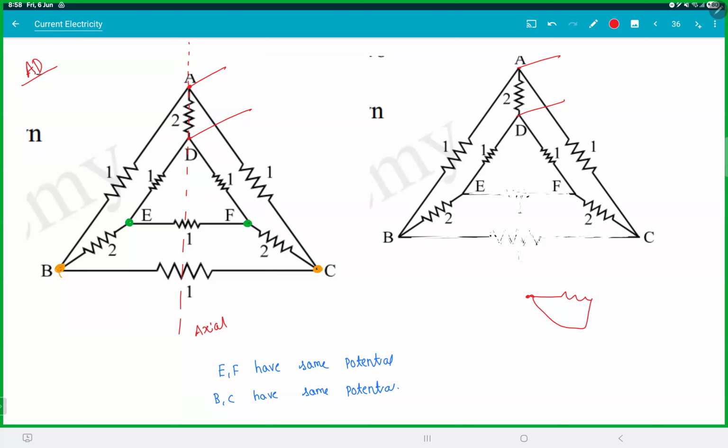Nere Vihan, that is wrong. Niharika, you got reverse. So you can remove the resistors in the middle. Be careful, don't use capacitor formulas here. Then you're done. Now look at this thing. This one, this two, and this one, all three are in series. Same current flows there. That becomes 4 ohms. So your circuit will look like this. The central resistor will be 2. The left resistor will be 4. The right resistor will be 4. RAD is 1 ohm. Check.